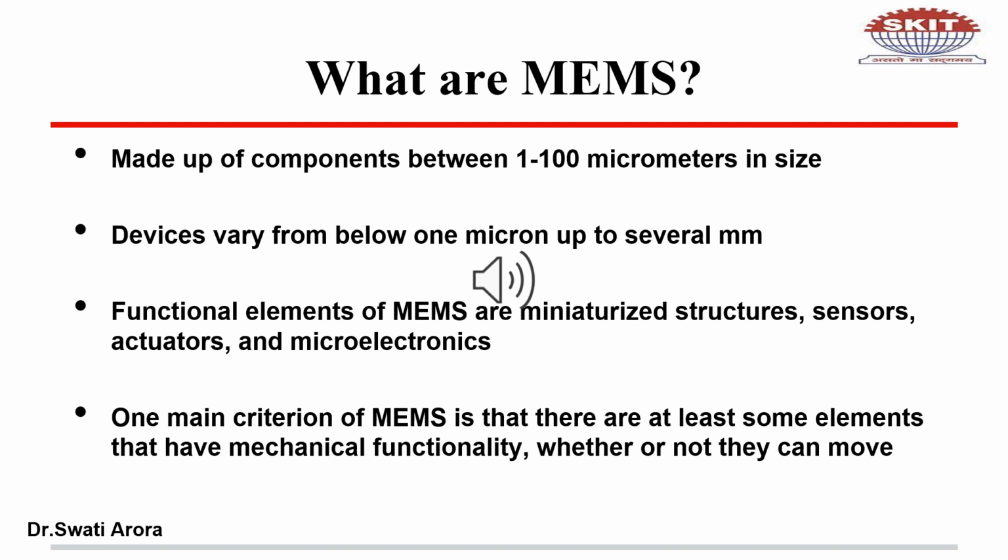It is a technique which consists of microelectronic elements, actuators, sensors and mechanical structure which are built on a substrate. Usually silicon is used as a substrate material. They are developed using microfabrication techniques like deposition, patterning and etching. The most common forms of production of MEMS are bulk micromachining, surface micromachining and fabrication. So the benefit of this small scale integration brings technology to a vast variety of devices.